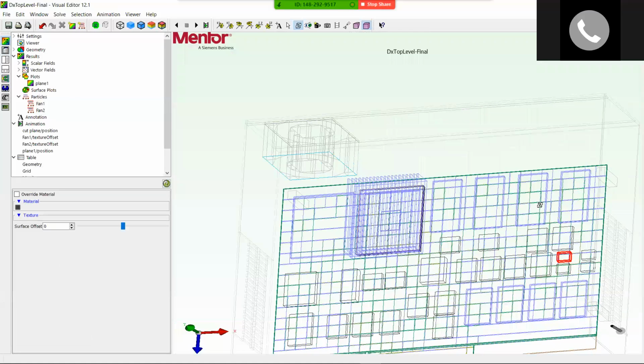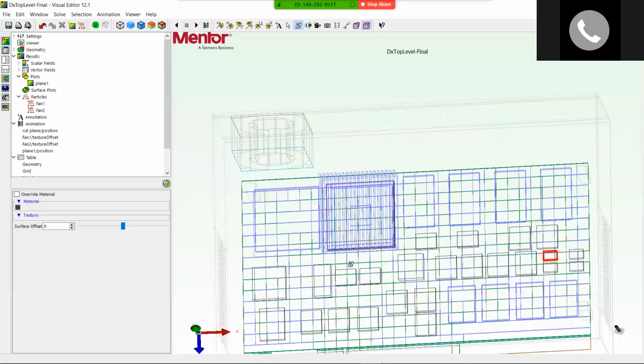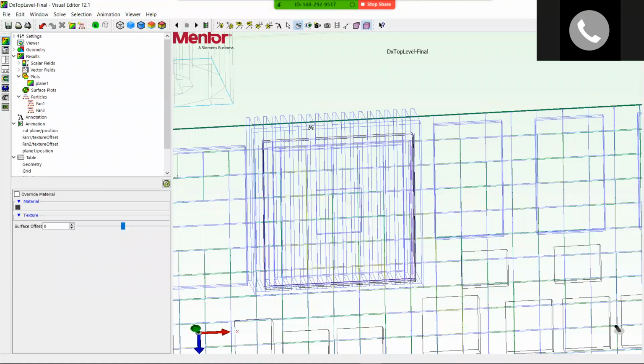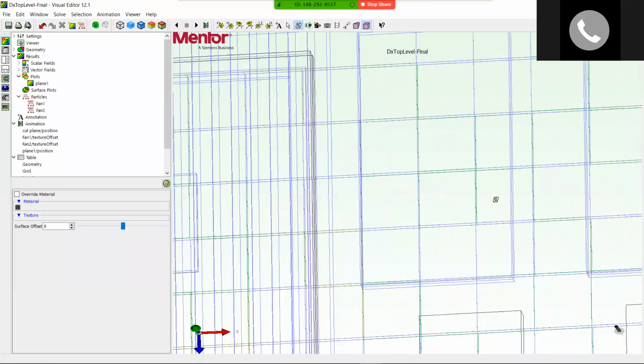Okay. So you are right that the location of the fan is not optimal. It should be right near here. And the other thing to notice is the fin, right? In this case, the fin alignment is this way, which is good. If you have the fin alignment the other way, which can be a common mistake, the air might not be as good as this way. But yes, you are correct.